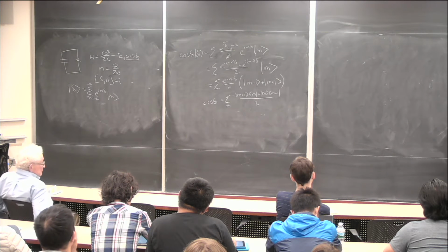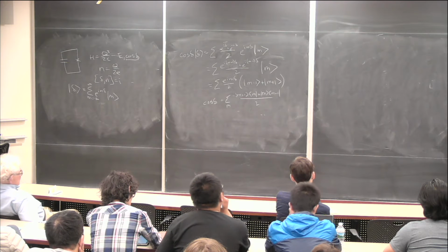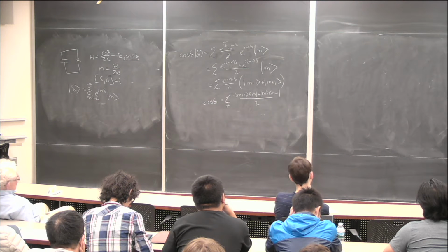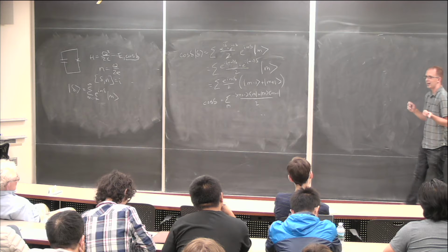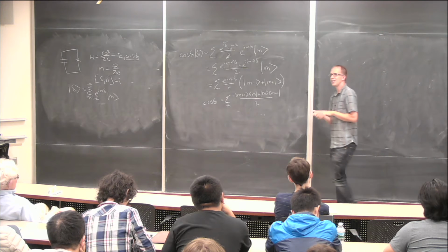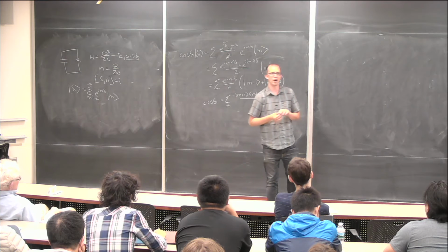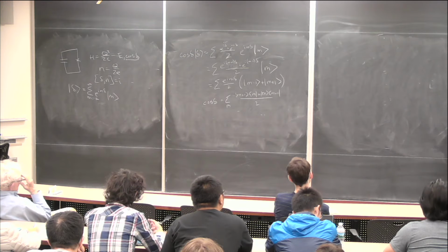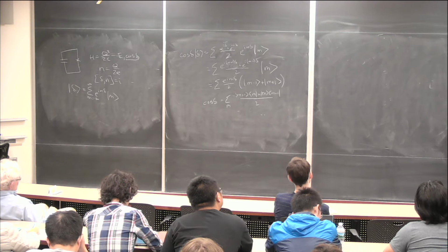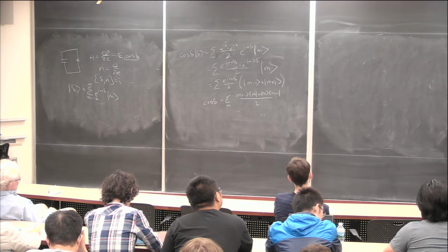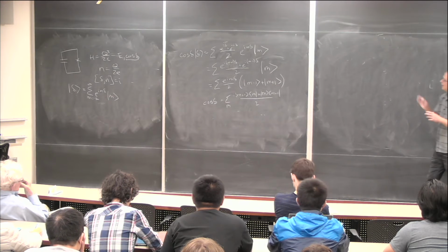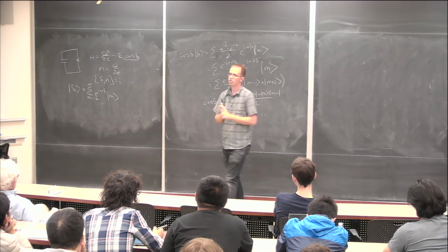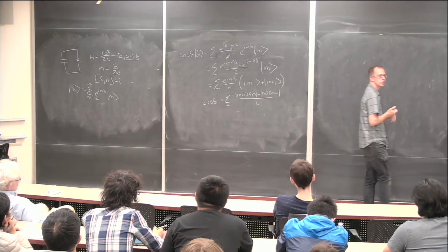Okay, so way back in 1997 or 1999, depending on exactly how you want to count it, Michel Devoret then at Saclay and Yasunobu Nakamura at NEC in Japan were concurrently working on a device known as the Cooper pair box. Michel's device was earlier, but he wasn't thinking of it as a qubit, and Yasu was the first to really call it a qubit, but essentially it's the same device, and it is this circuit with a charge bias attached in a limit where the Josephson energy is relatively small.